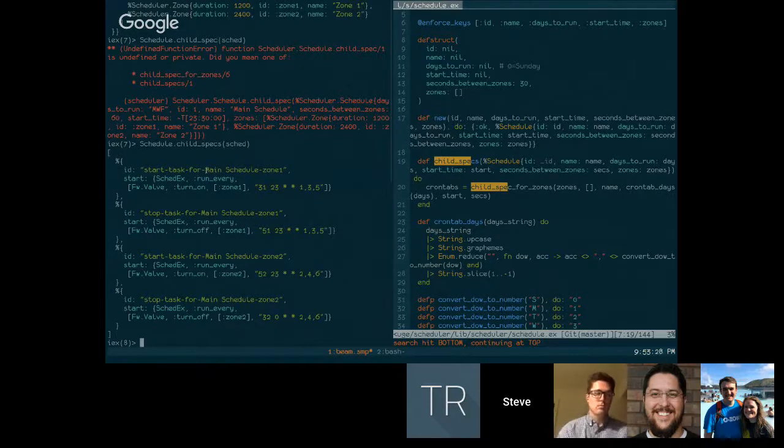And so you can see that I have a start task and a stop task for each zone. That goes to what I was talking about earlier, where it just seemed to make sense to me that I want to turn on a zone, and then 20 minutes later, 45 minutes later, whatever, I actually just want to turn that one off and assume that the default state for my controllers is off. So if I lose power to the relays, for example, it will open all the relays, and any sprinklers that happen to be on will get turned off. I haven't tested this yet, but I felt like I was safe just saying I'm going to turn on a specific zone, and then at the end of the time that I want that zone to run, I'll explicitly turn just that one off and not have to worry about resetting all the zones.